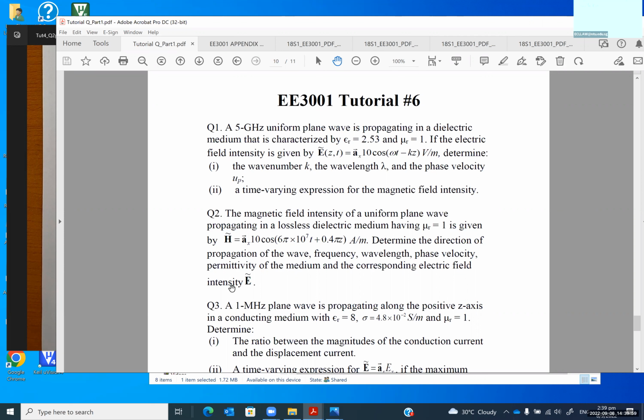So what creates this extra path? It can be like you put a metallic plate. When the ray hits the metallic plate, that sharp edge creates what we call diffraction. It's a secondary source, with rays going in all directions. The one that goes to your receiver is what you're interested in.